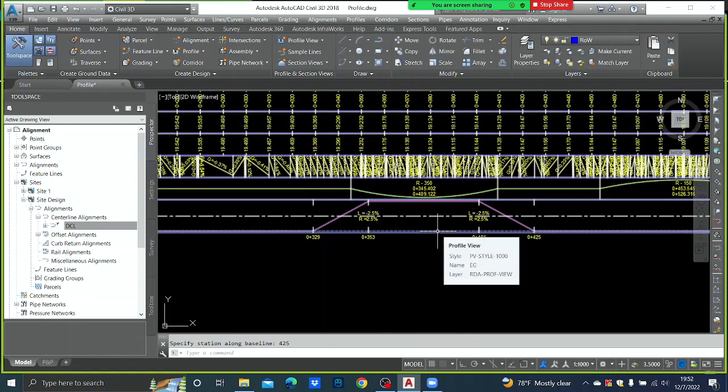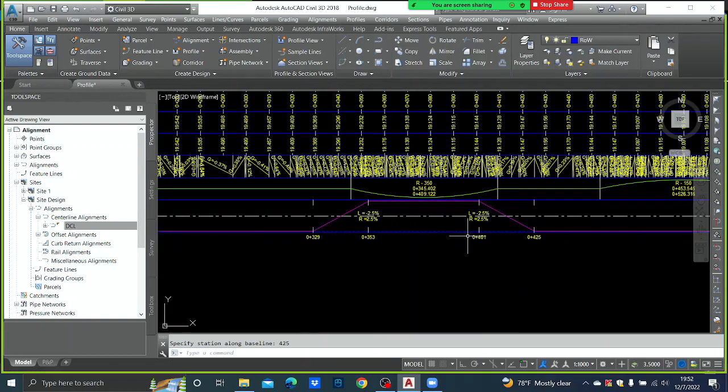Okay, so that is about how you can insert super elevation, and in my small booklet everything is there, including the jargons also. So you may be able to check what they are telling by end normal crown, begin normal crown, level crown, what are these things, because the software is using some jargons. Usually that is not used in our normal highway design textbooks.